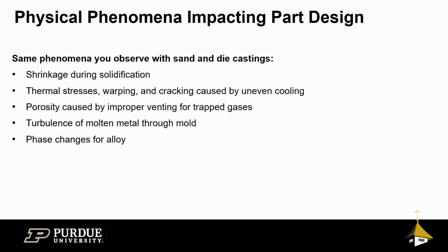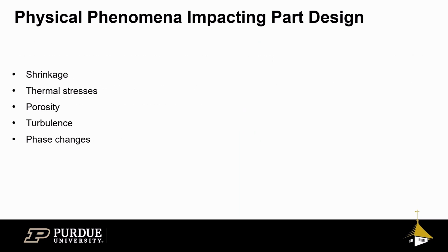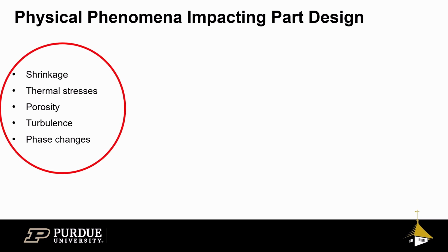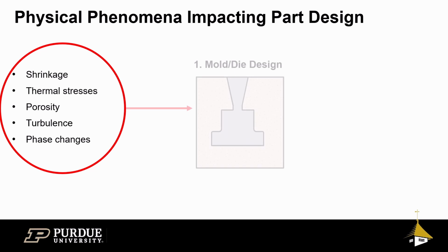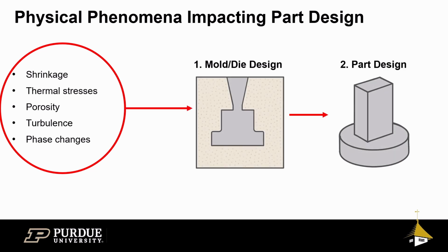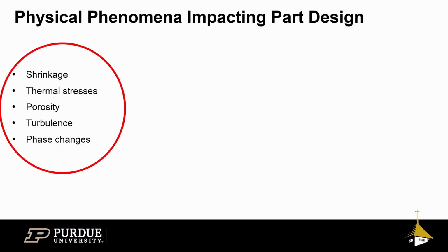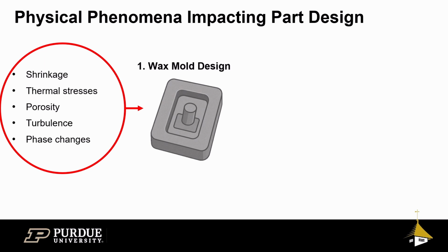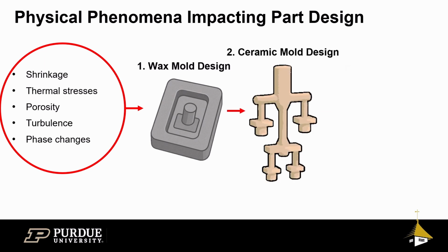The physical phenomena observed for this kind of casting are very similar to sand and die casting. These phenomena are nothing new, so I'm not going to spend too much time discussing these in detail here. But what we learned for sand and die casting is that these phenomena drive design decisions for both the part and mold design. Investment casting differs from this outline by introducing the need to design for the wax mold alongside the ceramic mold and the finished part.